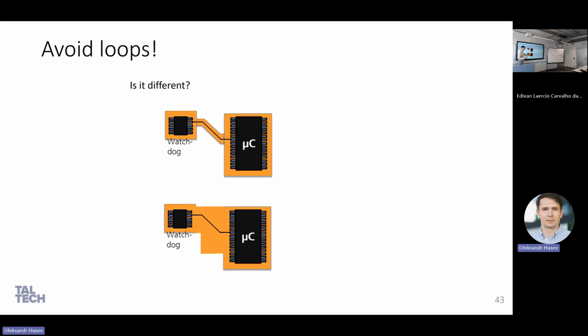By the way, this is also a stupid mistake because copper in PCB by default is present, and by technology of production, you remove it. So you don't save anything. Okay. But you decided for some reason to save copper and to put it like here instead of this, right? Or you didn't have place for that. It's another story, right? But does it have impact in terms of performance?